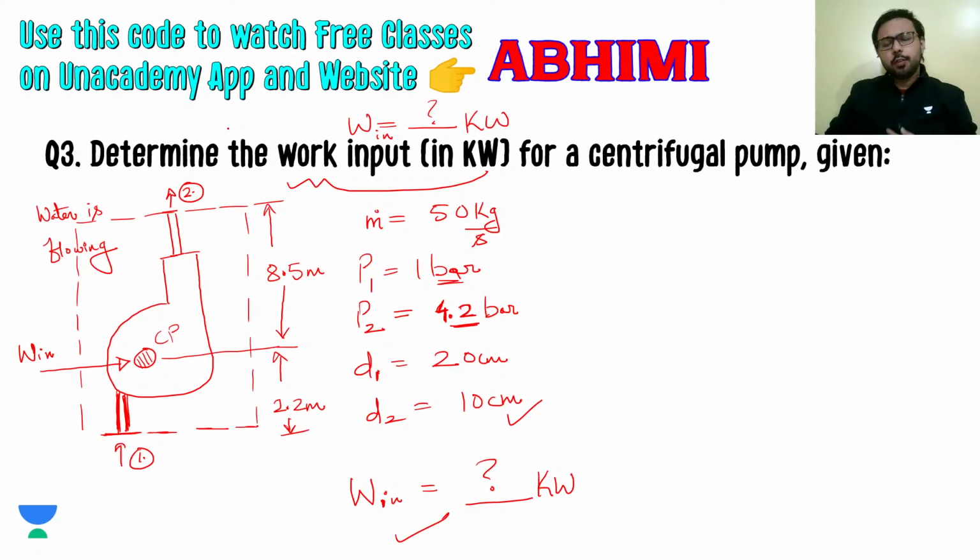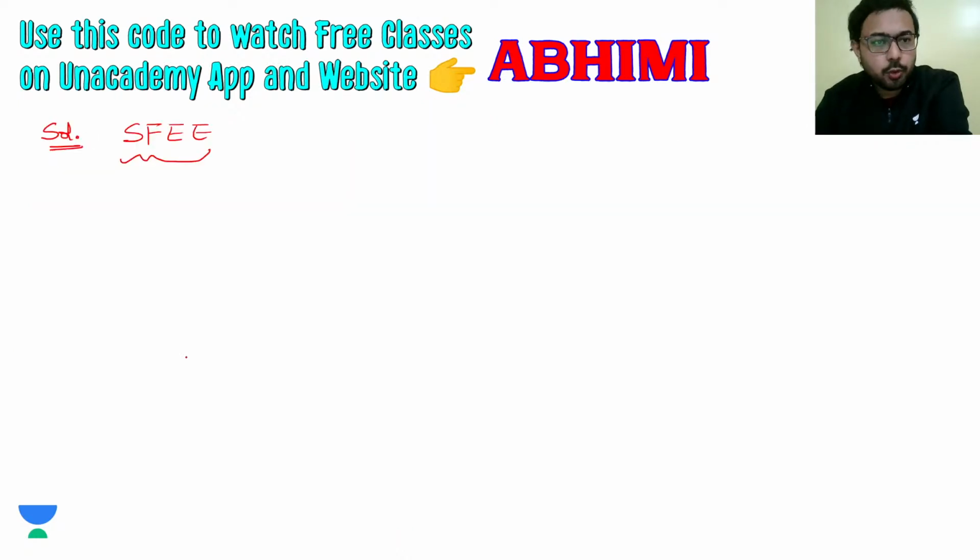Because we have to calculate work input, and this is a pump, so it will not be a closed system, it will be an open system, with mass flow going on, and the steady flow energy equation includes the terms that are going to be important in our calculation.